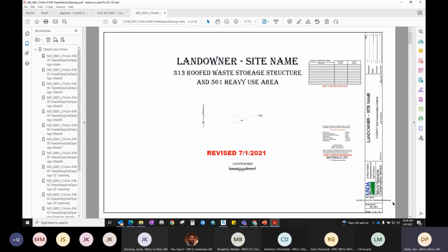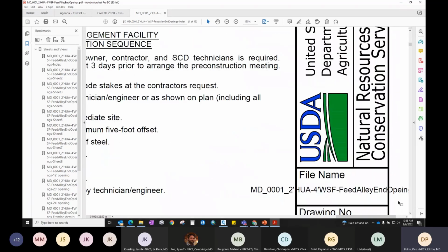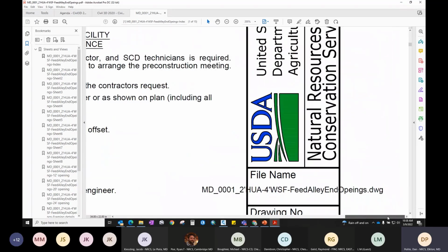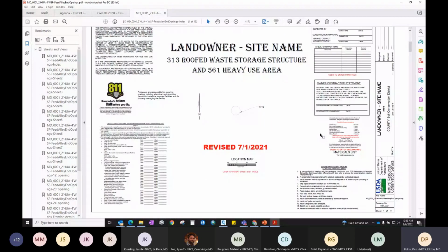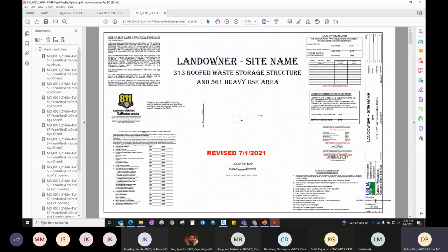Basically, what's happening is you'll notice down in this bottom right-hand corner, this is going outside of our title block. So I see a lot of drawings that when people publish their drawings, once this goes outside of your title block, this is not to scale anymore. So be very cautious in that.